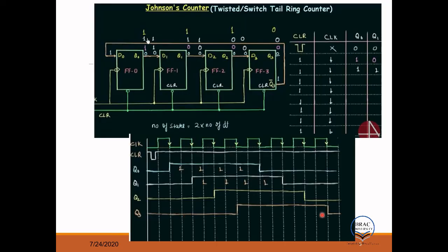Now actually, how are you getting these values? Just look here. All the flip-flops have 0 0 0 0 0. So what will happen when we are at this situation, where clear is 1 and the clock is activated, falling edge, right? Just here, these values become 1, and it's coming here, right? So this is 1, and previously the input here was 0, so it's going here. So these zeros go here, and again these zeros go here, these zeros go here, these zeros go here.